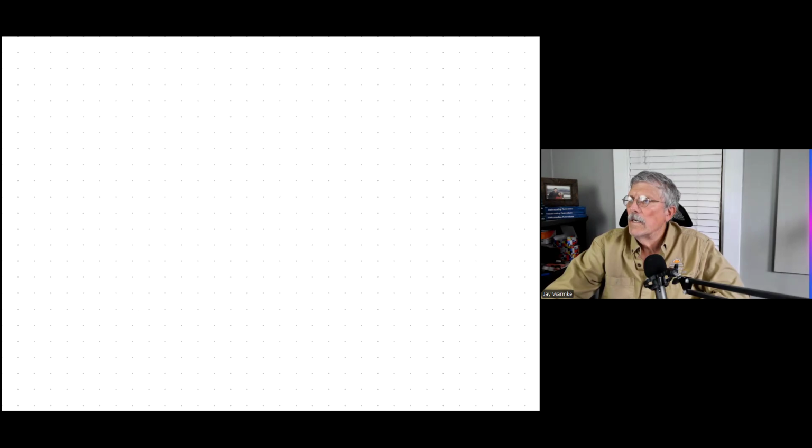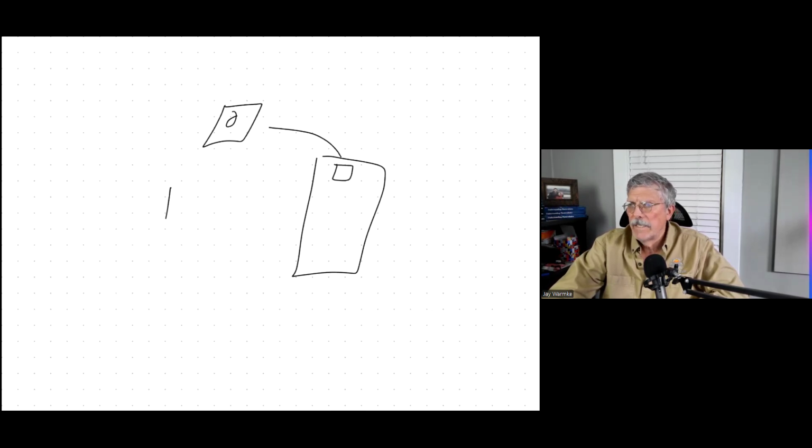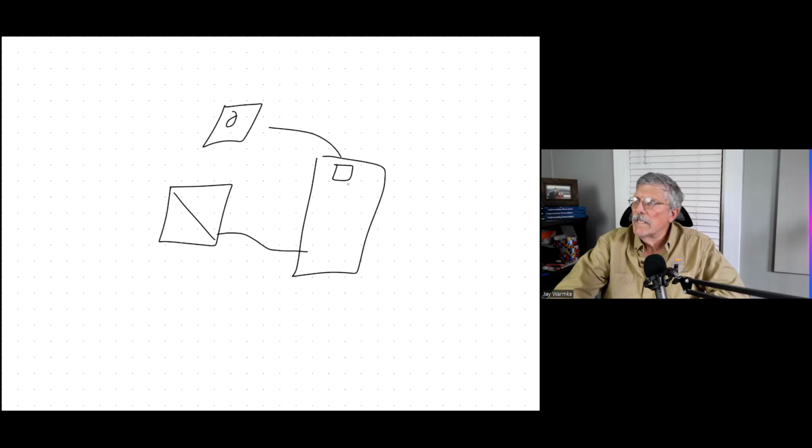So what is a load side? What is a line side? Well, if this is my service panel, and here's my main breaker, and it's going out to the meter, and here's my inverter, and I know there's an AC disconnect in between there, but I don't want to confuse things. If I go from my inverter on the customer side of the main breaker, it's considered a load side connection. It's on the load side of the main breaker.